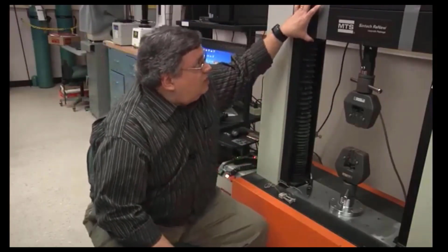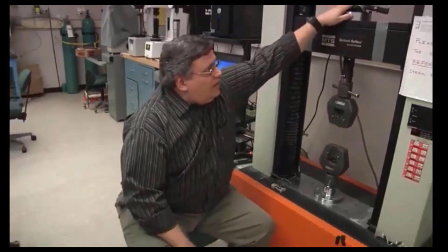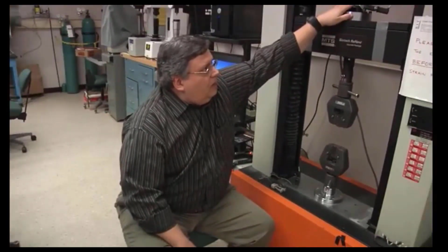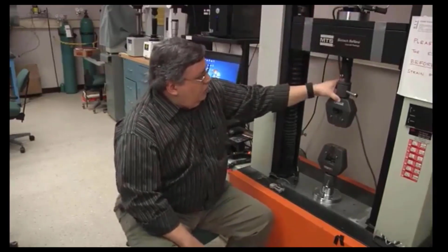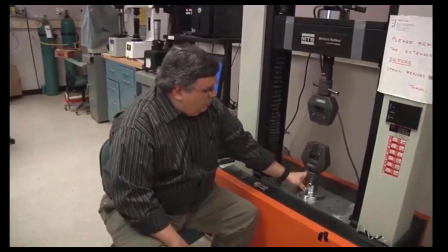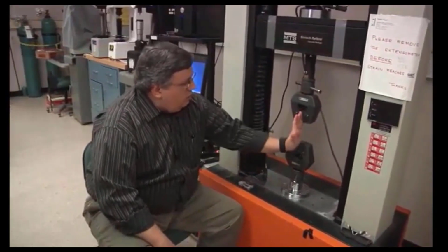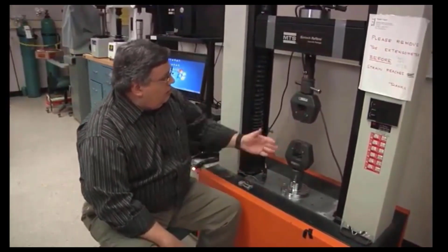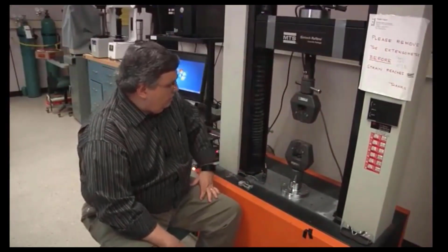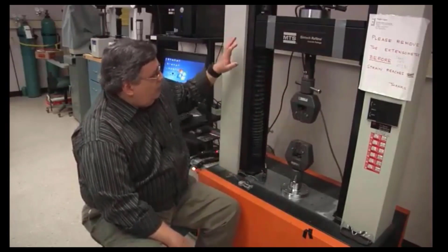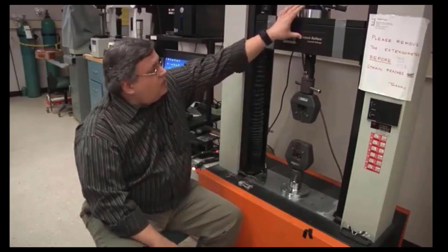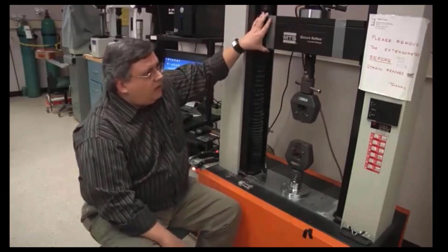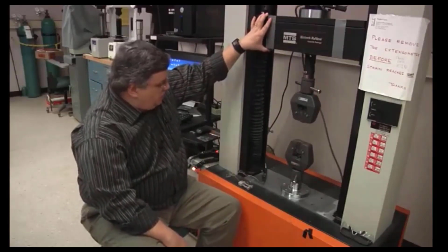For doing tensile testing, our load cell is attached to the top side of the crosshead. That's connected to a gripper. At the base, we have a gripper that's just fixed to the base. Our specimen goes in the center here, and we pull on the specimen. The instrument will record from the load cell. It records force versus time. From the motion of the crosshead, it records distance versus time.